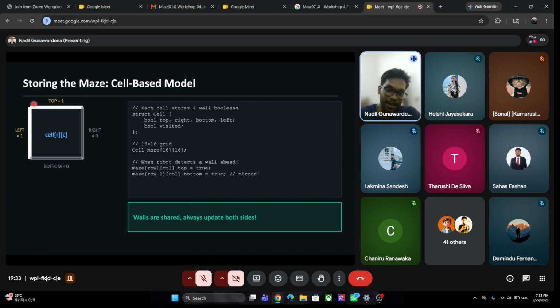When we are applying the flood fill algorithm, a conflict arises. You will see where the trouble arises when I teach you how to apply the flood fill algorithm. The flood fill doesn't know that there is a wall. It knows there is a wall with reference to this cell, but it doesn't know there is a wall with reference to the cell above it. So there is a conflict, the flood fill fails, and it doesn't converge.